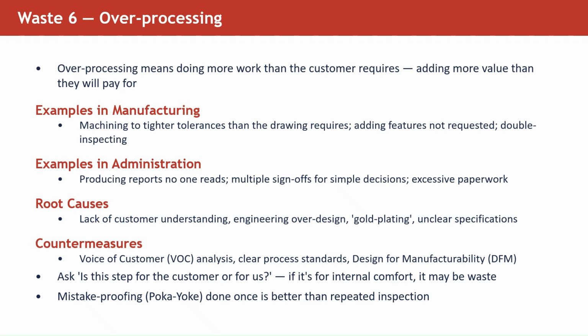Now, is this step for a customer or for us? Let me know in the comments. If it's for internal comfort, it may be a waste. Mistake proofing can be done once, which is better than repeated inspection. So Poka-yoke is the concept that needs to be implemented when we are designing a process.